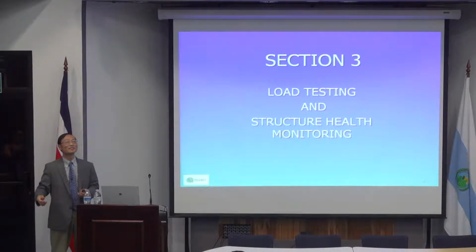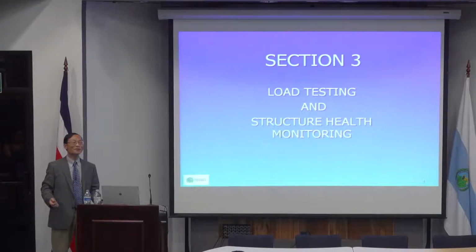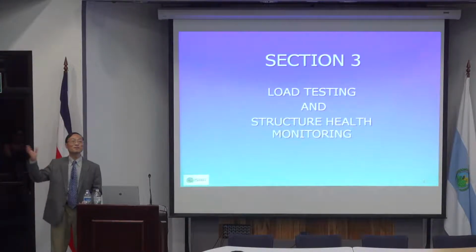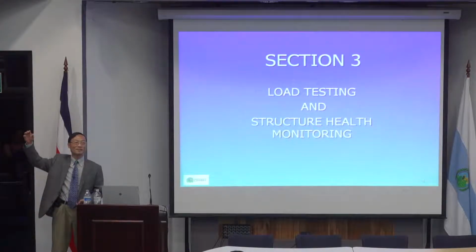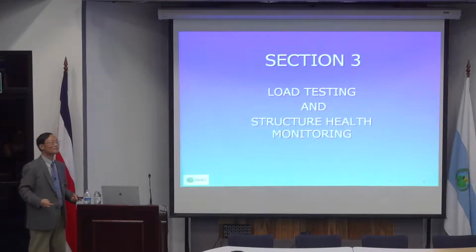So if you have that deduction, effectively you increase your loading capacity by rating factor by 20%. That's a very, very significant improvement. You can also do a test. You just have a regular truck, just pass by it, and measure the stress or deflection, and compare with static load, to see what magnitude of magnification is. In other words, if a static is 1.2 and you get 1.5, which is 1.5 divided by 1.2, that will give you how much dynamic impact component is.